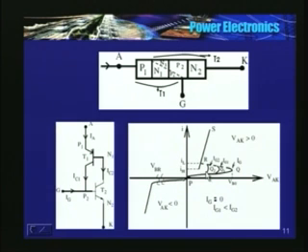And once the device current is higher than the latching current, gate has no control. So I will repeat, by supplying a positive gate current, the device goes into conduction mode. Okay.